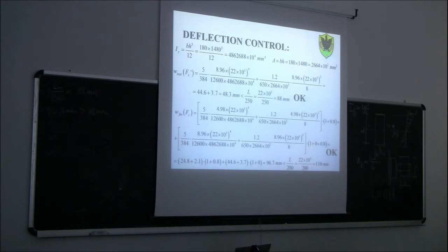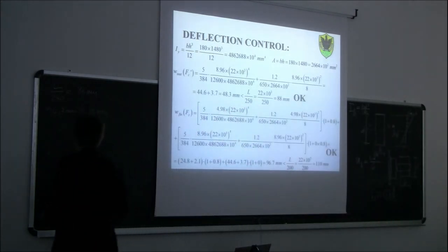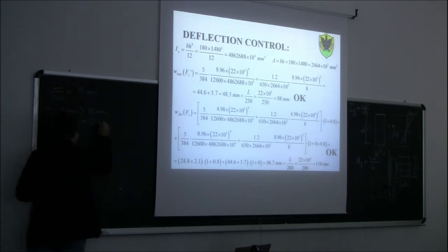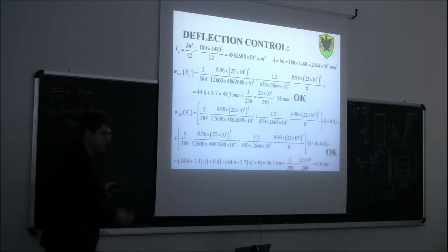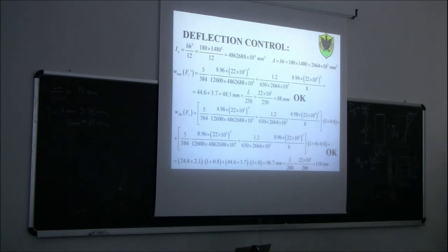And then of course when you do the verification you need to make sure that you have a little bit of margin. So for example, suppose that you change the breadth and then, instead of 96.7 millimeters, you get 88 millimeters, which is equal to 88 millimeters. Okay? In this case, are you satisfied if you haven't increased the self weight? No, because you are on the limit, unfortunately. So even if you increase the self weight a little bit, this would translate into 89 millimeters, for example.